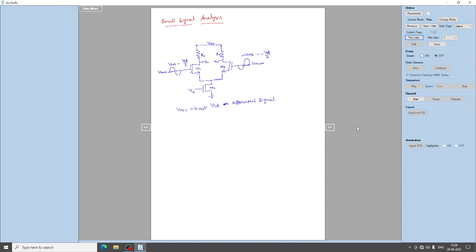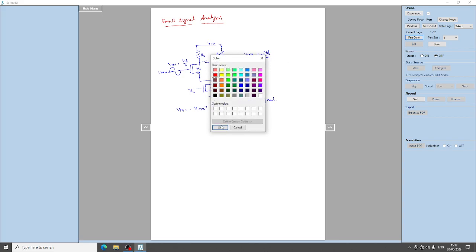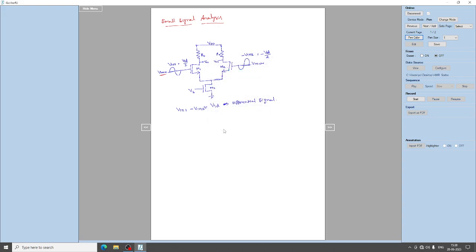So note that before that we have already biased the transistors M1 and M2 by giving the common mode input, right. Common mode input means this Vin CM. This is a DC analysis where we have fixed the input DC level, and it is not a fixed value. You have a maximum and minimum limit, right, what we have discussed here.